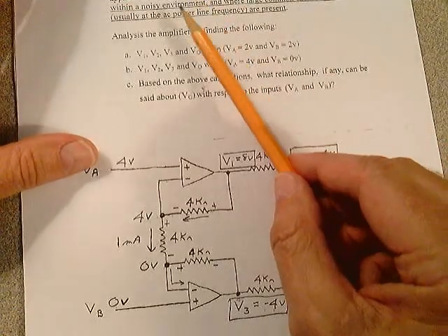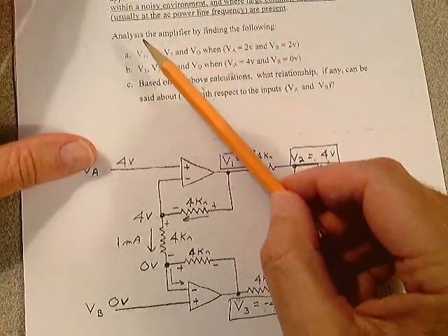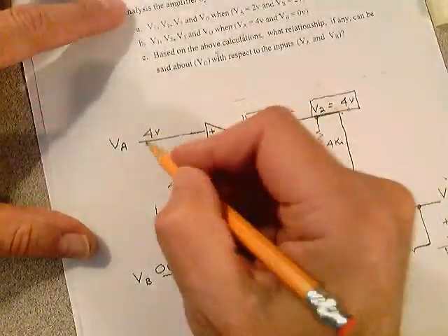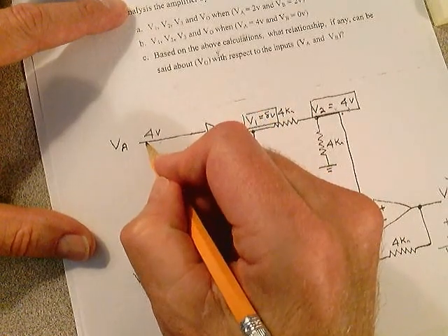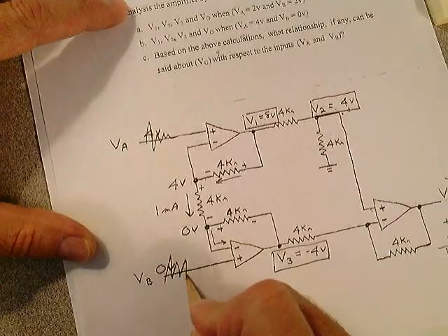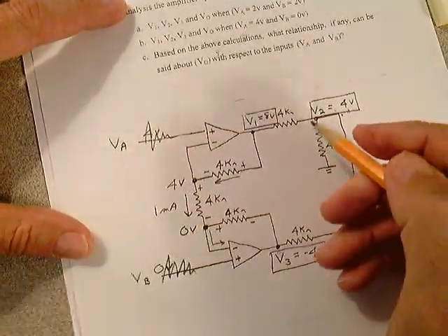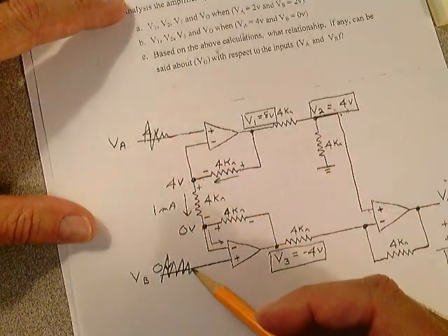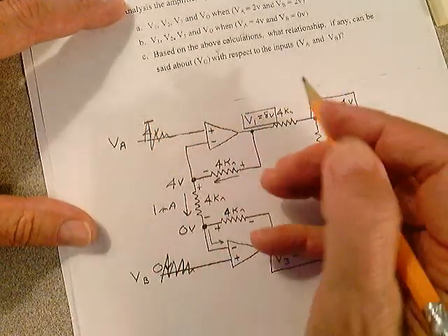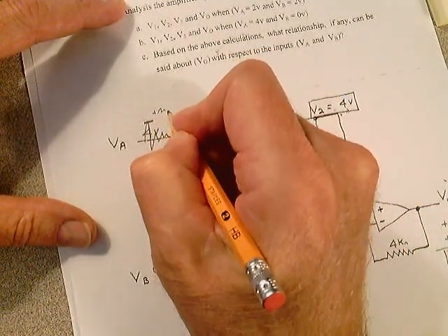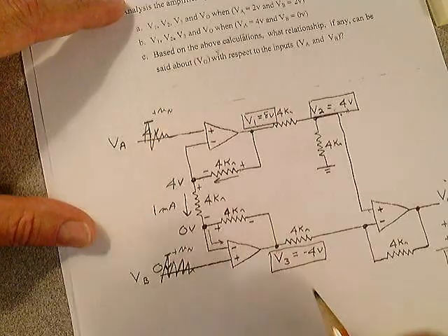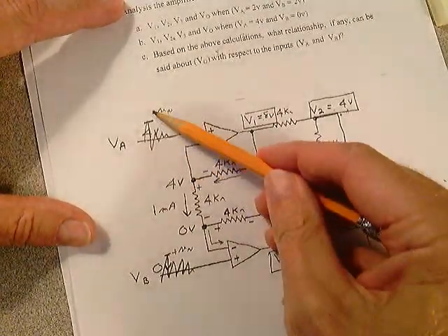Now, why we said that is so popular in many industrial measurement, data acquisition, and medical applications is because if you have any noise, we talked about noise up here, but if you have any noise riding on this, and you'll have noise, white noise, or 60 hertz electromagnetic interference. Notice that this wire and this wire are in proximity to one another. So if you're jumping up here with the voltage, call that plus V noise, and you're jumping up here with the voltage, let's call that plus V noise, do you understand that this instrumentation amplifier takes the difference of those voltages?